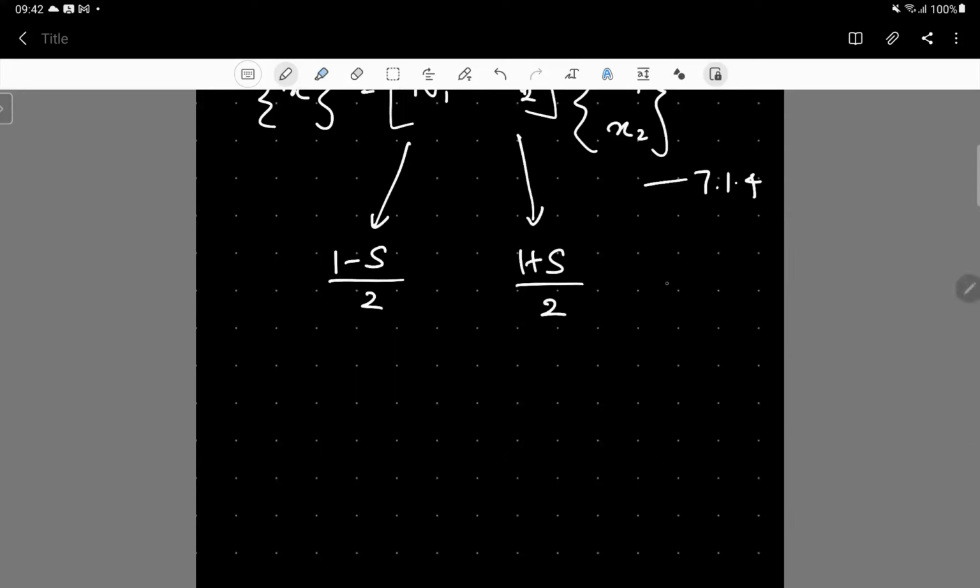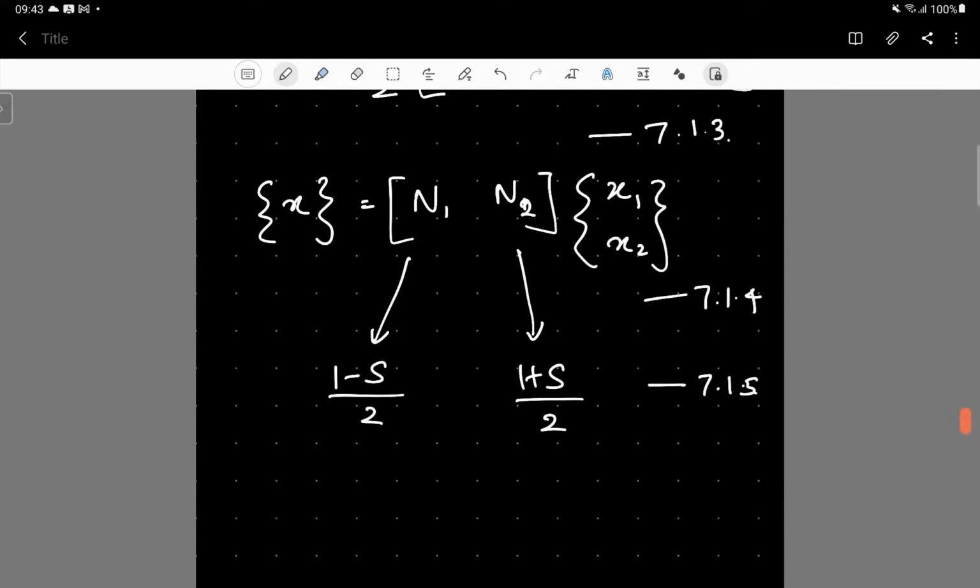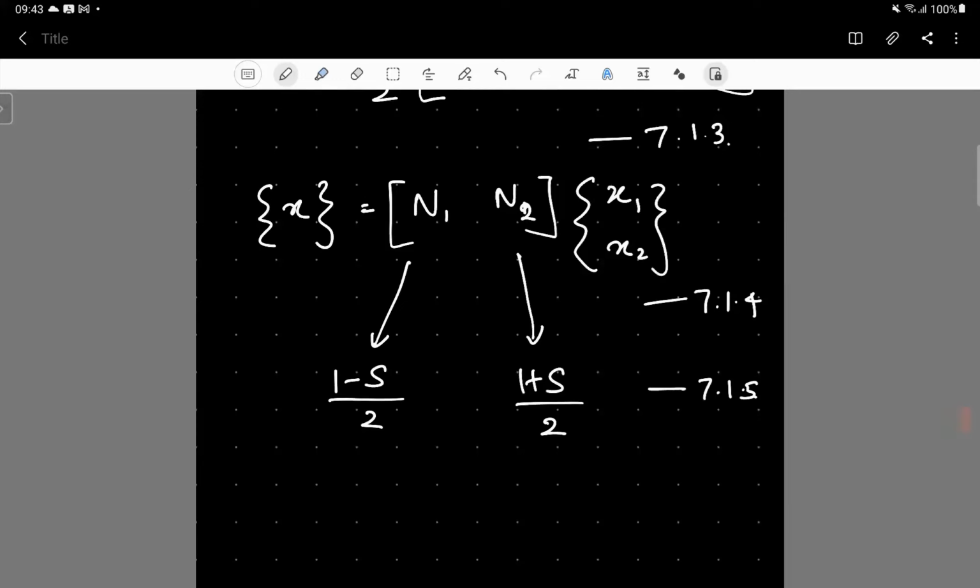So you see we have used two linear functions to map the s coordinate of any point in the element to the x coordinate, which is described in the global coordinate system. If we have done the arithmetic correctly, when we substitute an x1 value into this equation, we should get the corresponding local coordinate, the natural coordinate, as s equals minus 1 in the natural coordinate system.